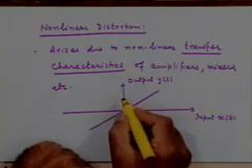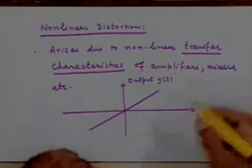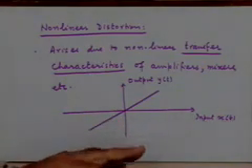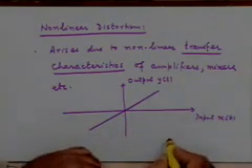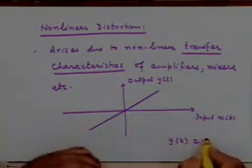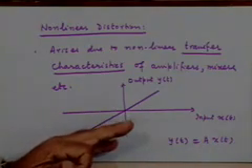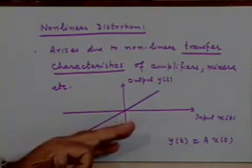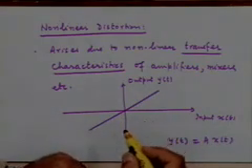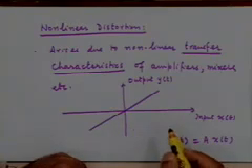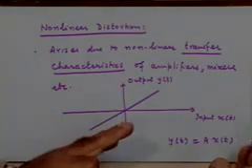Input is small, output should be small. Correspondingly, if the input is large, the corresponding output should be large. Simple. Nothing beyond that. So it's a constant times the input. Ideally y of t should be equal to some a times x of t, where a is the amplification factor, right? That's the transfer characteristics. Now practical power amplifiers will exhibit a kind of nonlinearity which is very commonly encountered, called